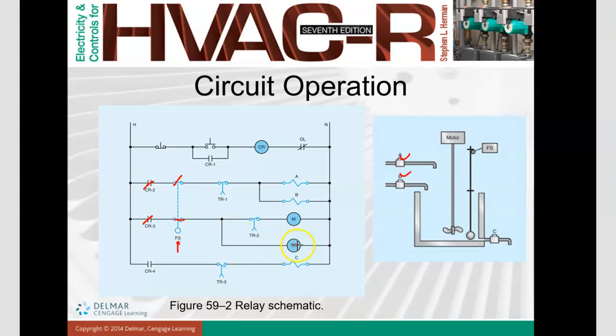Okay, at the same time, this is time relay. Time relay starts functioning. You set it to 1 minute perhaps. Okay, so after 1 minute, it will energize. Okay, after 1 minute it will energize. It's not directly energized like the other coil. This is also a coil perhaps. After 1 minute it energizes.